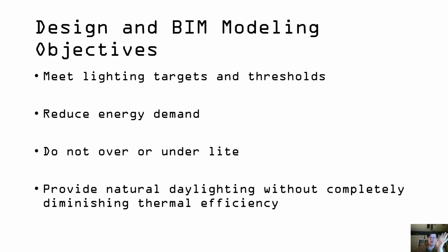If we have the center of a room, like with this skylight, providing all this natural daylight, but the walls are dark, it creates a very uncomfortable condition. So generally we want what's called uniform lighting within zones of a building. That's also why a number of naturally daylit buildings will have supplementary electrical lighting, normally there to create more of an equal balance throughout a space.